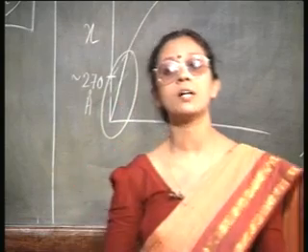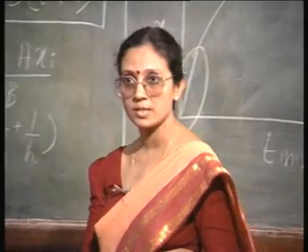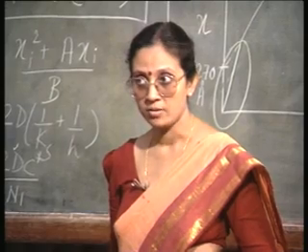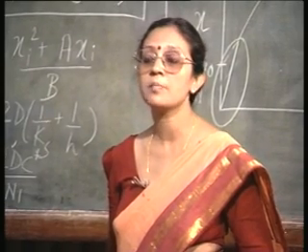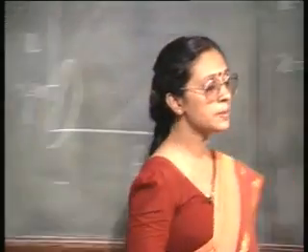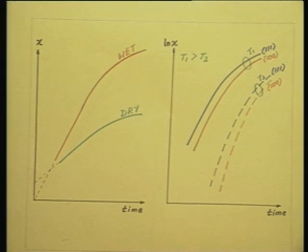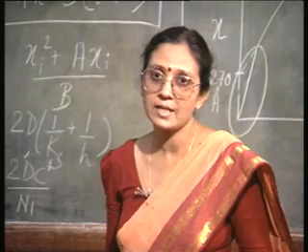The oxidizing species now must diffuse through the existing oxide layer and then reach the silicon dioxide interface. So, the oxidation rate is governed primarily by the diffusion. That is why you see, as time progresses, the two curves tend to come closer together. So, particularly in the linear regime, you find there is quite a considerable difference between 100 and 111 oriented crystals. However, as time progresses, the oxide thicknesses tend to catch up with each other.